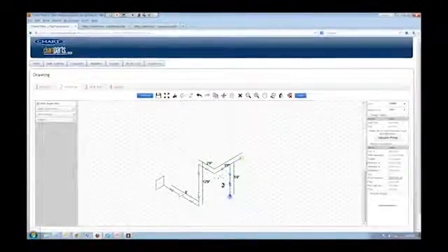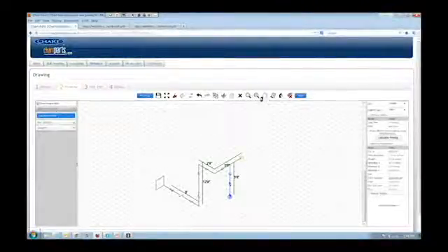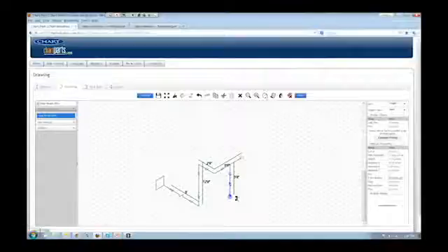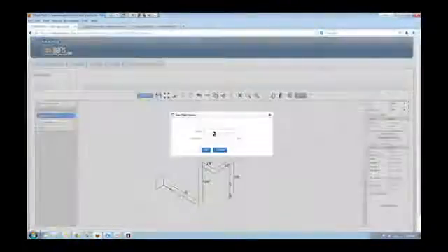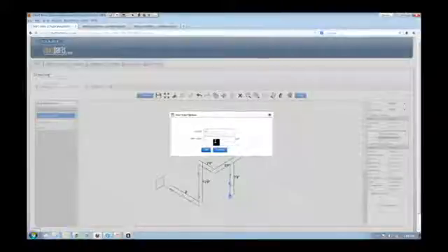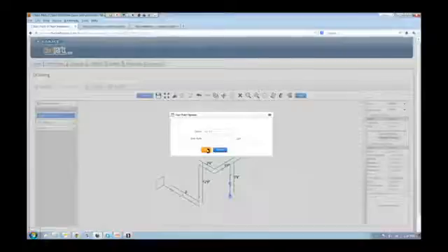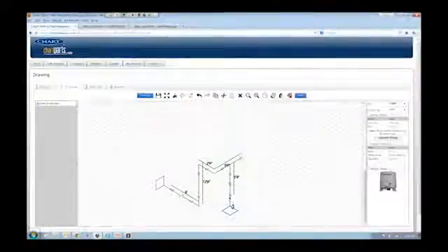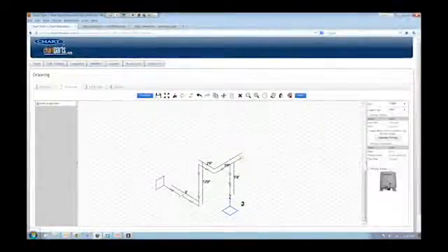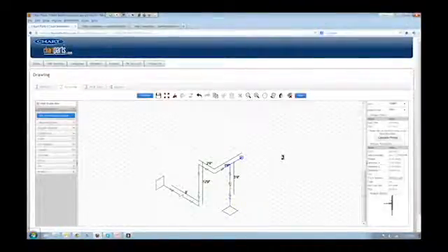While I'm here, I'm going to terminate this with the application point. In order to calculate pressure drop, which is this symbol right here, I need to terminate it with a use point. So this is going to be my O2 clean, O2 number 1, and we'll say it's got a flow rate of 1 GPM. Okay, so that really defines that leg of the circuit. Now I'll switch application points, and I'll continue on with my design.